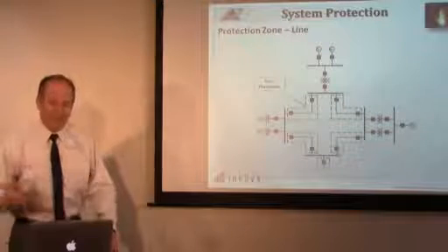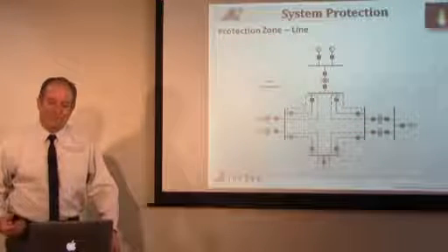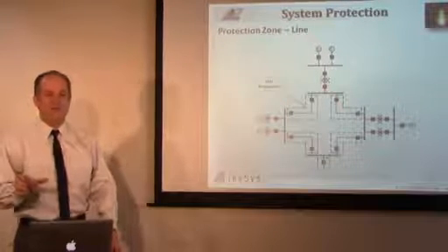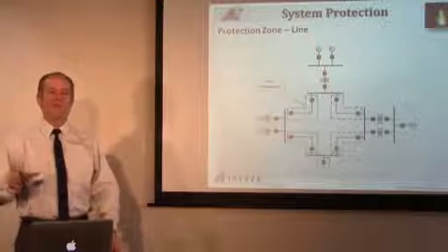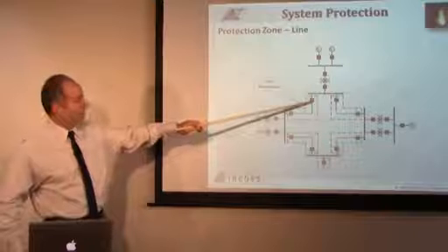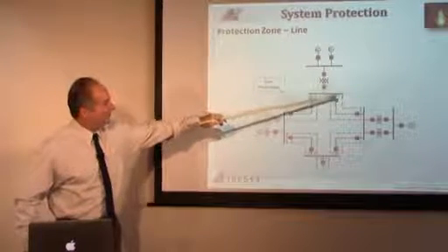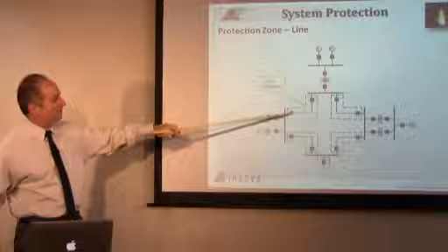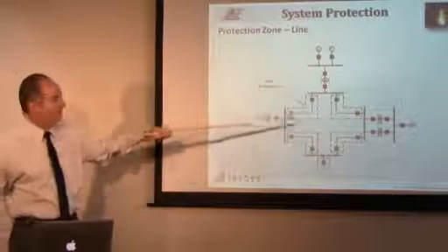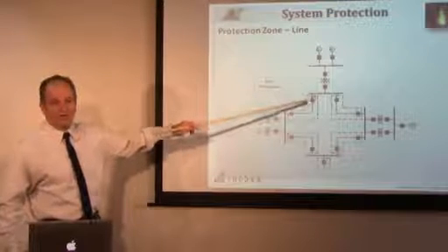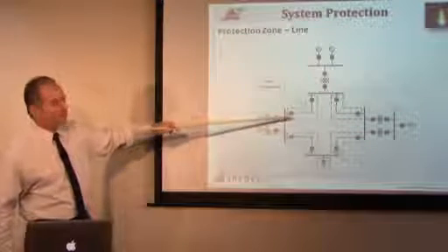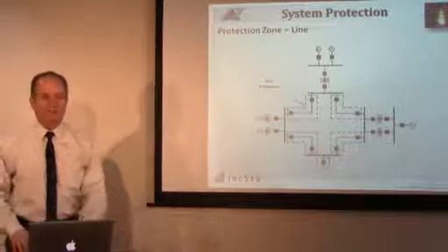The breaker itself failed, okay? And if that's the case, then if the current in that CT doesn't drop to zero in a predetermined time, then all the breakers associated with keeping that breaker energized are tripped. So in a case like this, if that breaker does not trip, then we have to trip that breaker, and remotely this breaker, which might involve telecommunications systems in order to tell the other breaker to trip. That current has to get to zero or it's a breaker failure. So we use the CTs on the opposite sides in order to protect that line, because it also includes protecting the breaker.